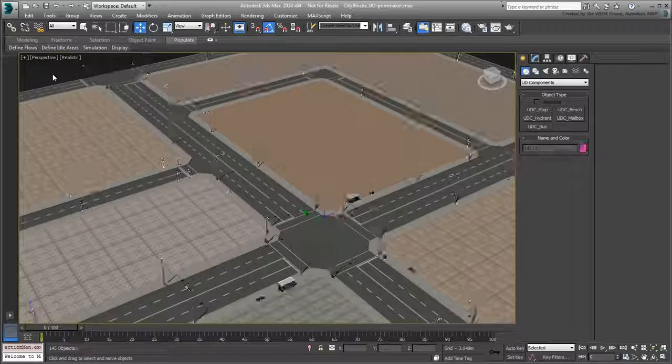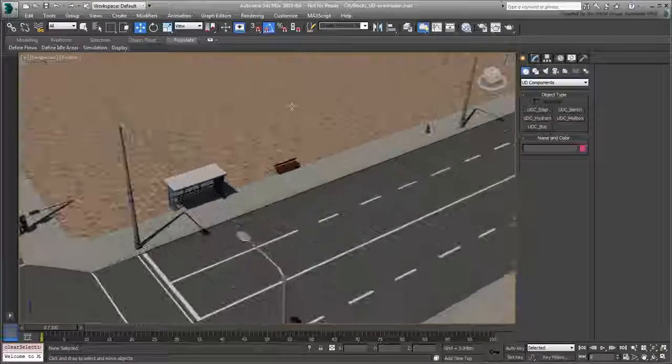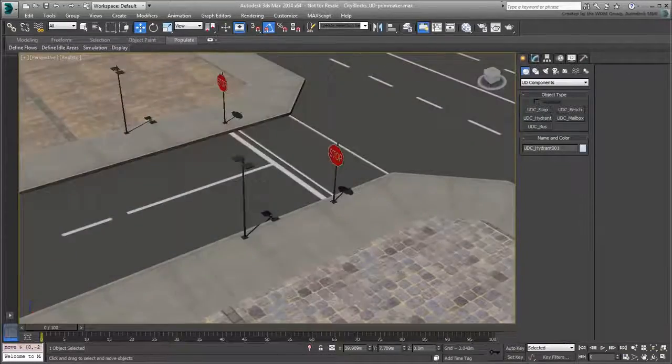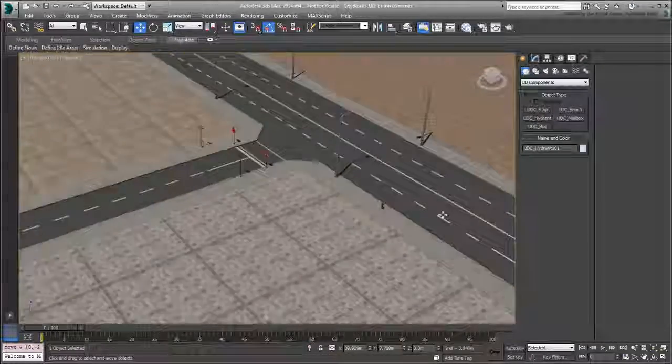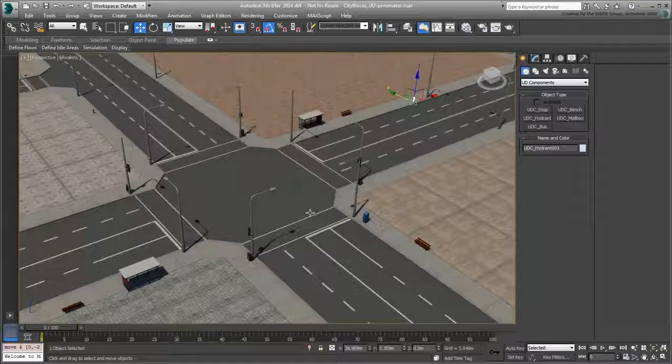There's one final note you need to be made aware of. The way you learn to use Primitive Maker in this movie is session-based. This means if you were to exit and restart 3ds Max, you would lose the UD Components Primitives panel. In the next movie, you'll learn how to make it permanent.